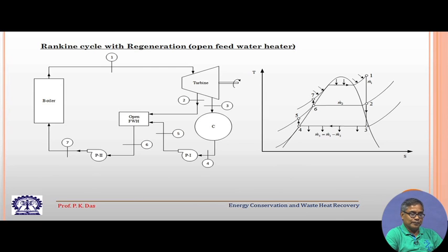that will be less, because part of the steam we are not using for producing work, we are using for heating purpose. So, obviously, that will reduce, we will see how to take care of that, but we will have a definite, good increase in the efficiency of the cycle. So, that is the key point of our regenerative feed heating or regeneration, and that is what is adopted in all the practical steam power cycles, all your utility power plants,